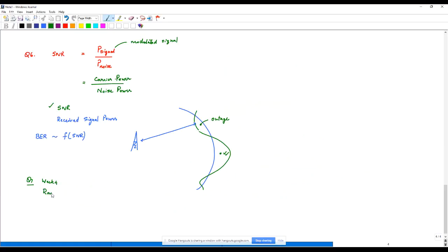We've been looking at Rayleigh fading: what are the characteristics of Rayleigh fading, the statistical description, and what are the properties. One of the key elements is the bit error rate in fading. This has some analytical steps that are needed, particularly integration, and sometimes the integration is not straightforward. You may have to do multiple steps, substitution. But this is one of the most valuable insights that you can get in the context of wireless communication.